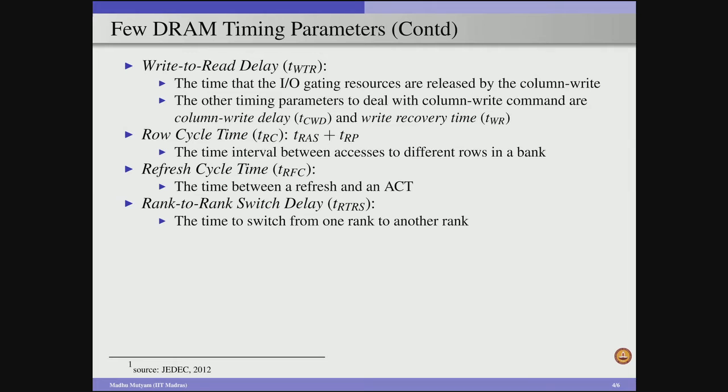For example, if the DRAM device has 8K rows associated with it, and as specified by the JEDEC standard, for each DRAM device we issue 8K refresh commands. So, for each refresh command we can refresh one row. As a result, our TRFC is going to be the time associated with refreshing a single row. When I say refreshing a row, we have to read the data from a row, restore it back, and then perform a precharge operation.